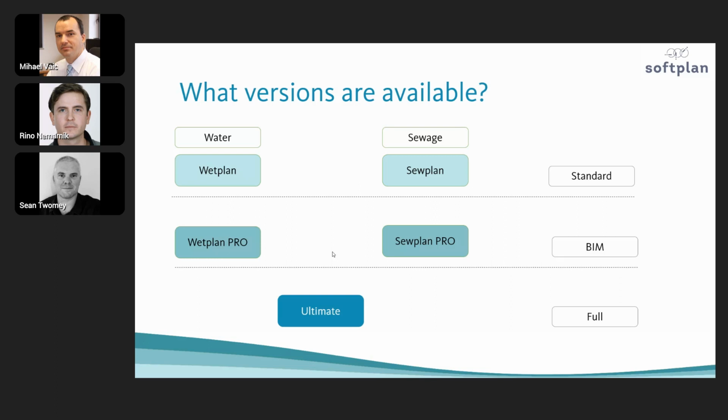You can do some surveying functions and basically geodesy functions, but the great feature about that module is that you can design alignments, and for those alignments you can draw cross sections, which are very similar to road design cross sections, and in those cross sections you can see the real terrain elevations. You can show multiple terrains, and multiple pipelines, and you can parametrically design trenches for multiple pipelines.